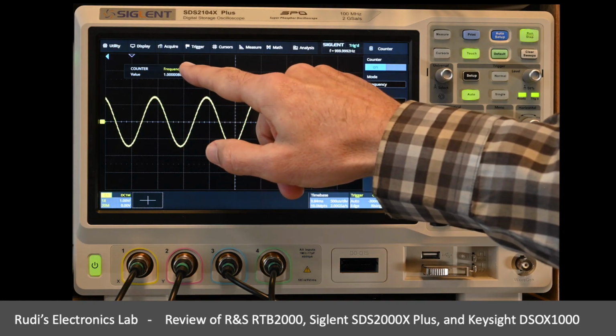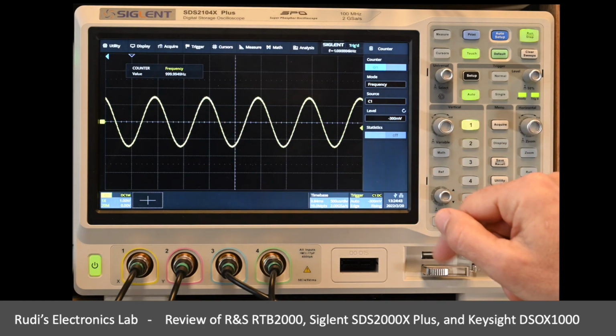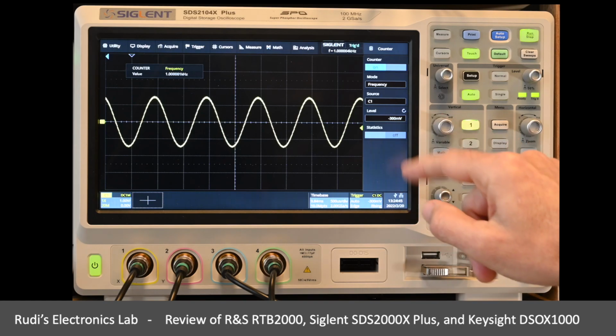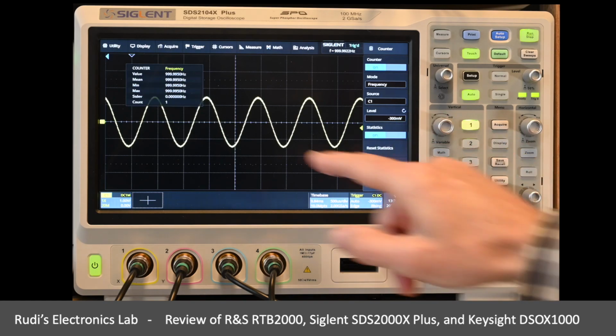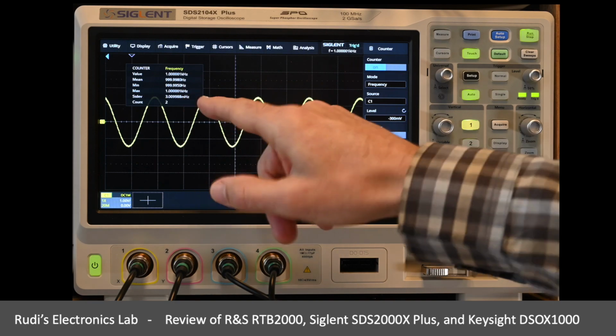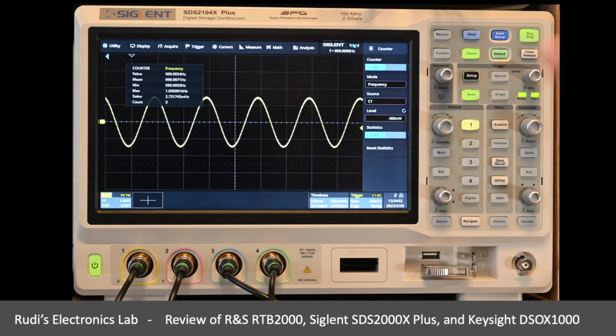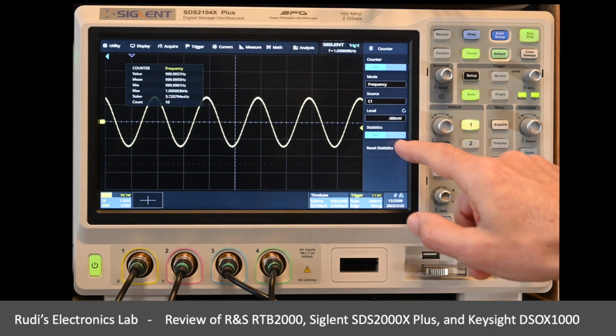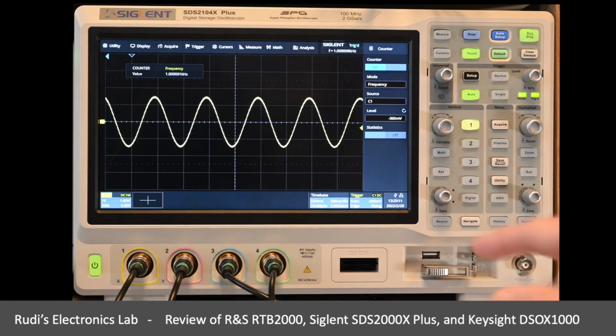So if we take the frequency counter, we can drag it around on the screen, we can set a level. We got statistics here. The other devices don't have that, so we get to see rather basic statistics. The statistics update rate is fairly low. It's only once every 2 seconds. The update rate of the frequency counter itself should be considerably faster. I think the manual says that it's like 100 updates per second or so. Only the statistics are much slower.